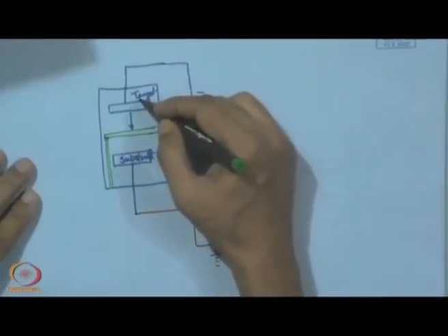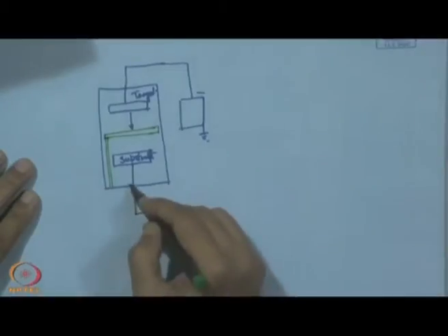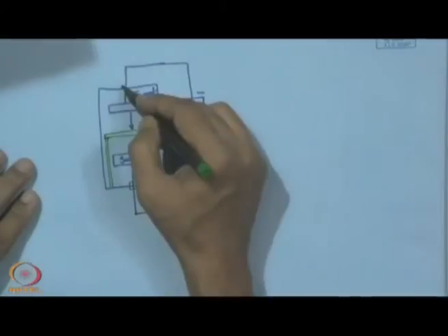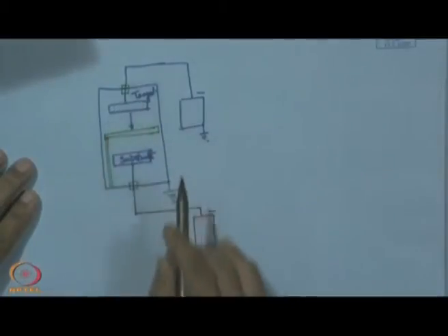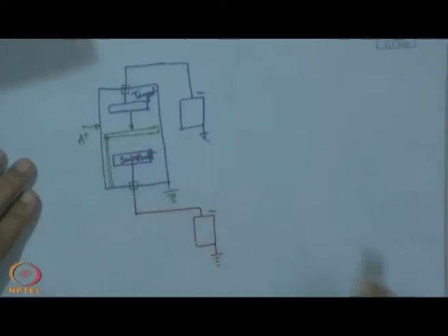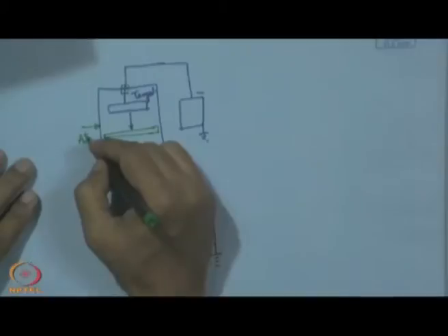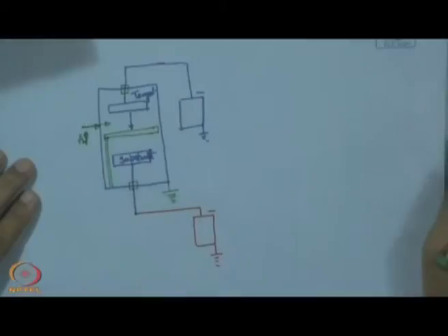Now, just like the shutter, which will be negatively polarized, similarly the substrate is also negatively polarized. These are electrical isolations, and this can also be grounded. So, these are electrically isolated from the chamber, and obviously here we have a precisely metered quantity of argon gas which is admitted. The rest is according to the principle of sputtering.